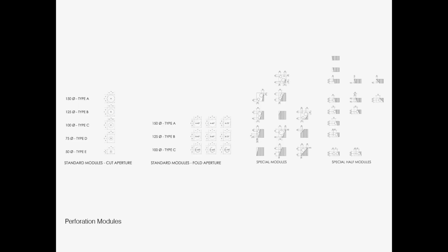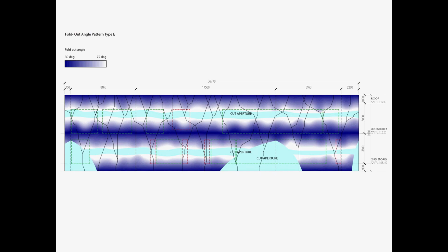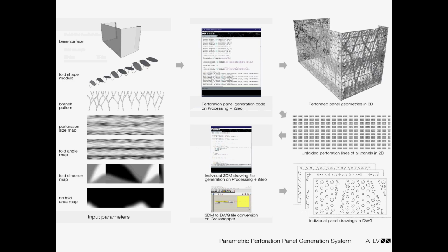First I started with generating tree patterns, because they were interested in a certain kind of computationally generated tree pattern. But later, stronger constraints came in from the fabricator, who produced the perforation out of a limited set of dies, so the type of hole we could use was limited. Later the branch or tree image was simplified, but I tried to manage the hole size, and the extruded tab also works as a solar shading louver, so the orientation and angle can be controlled.